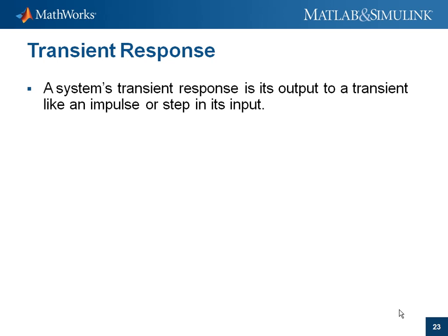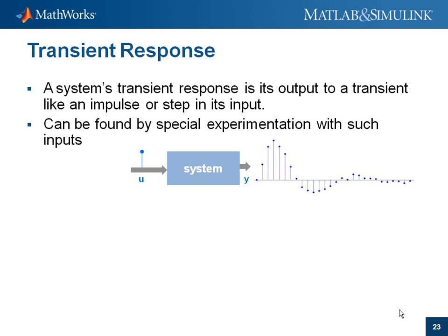The transient response of a system is the output where the input is a short pulse or step. Of course, this transient response can be recorded directly from an experiment where the system is subjected to a step or a pulse in the input. In fact, simple step response experiments may be the most common example of identification experiments in practice. It is in any case a very valuable first stage in understanding system dynamics, typical timescales, delay times, and similar.